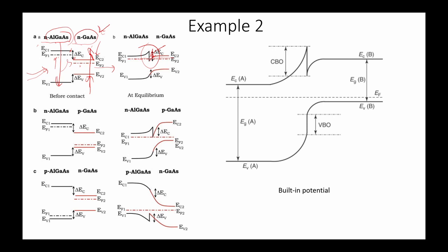So at any temperature we can find electrons at this junction, because the Fermi level is such a level. At 0 Kelvin, all the states below the Fermi level are filled. So finding an electron at this point is 100% probable. There is a 100% probability of finding an electron at this junction.